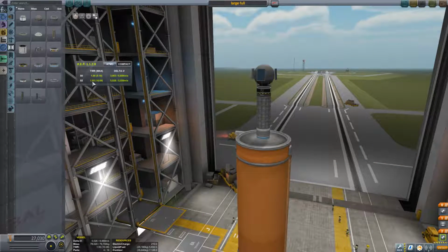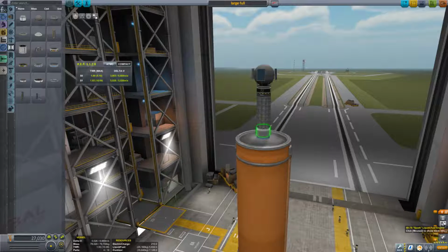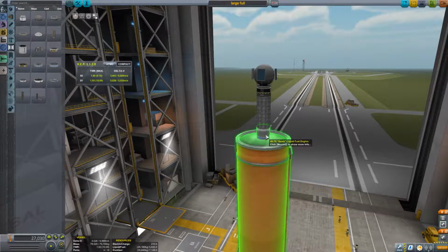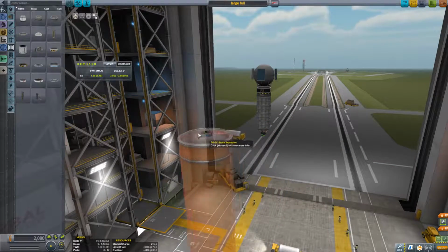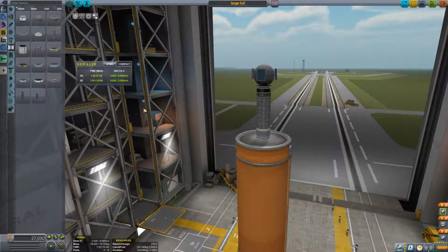Now it shows two stages. The first stage that will fire is the highest number because we're going to count down through the stages as we click them. So we will start with 1.93 on the launch pad, and we'll eventually get up to 10.09. And then when we fire this engine, as we decouple, I can go ahead and combine these. Now it's stage 1 and stage 0. This will have 1.8 thrust weight ratio, which if we take this off, it still does. So the major difference is we've increased the total amount of this thing called delta V.